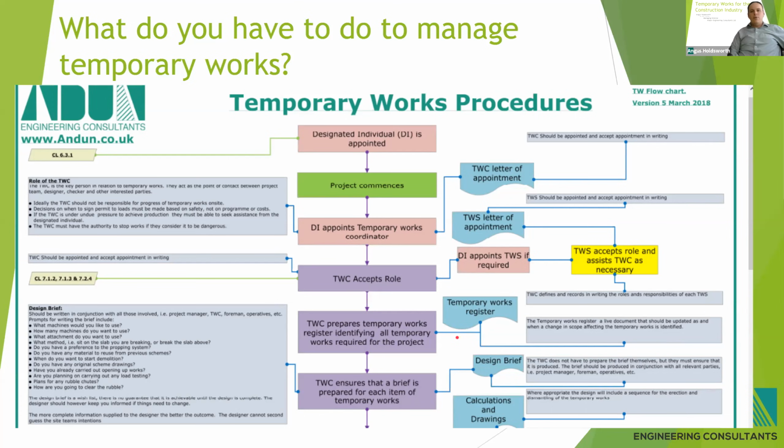So the onus is on the TWC and the designers to say that I think this needs a high level of check, and there is lots of guidance available on where things should sit in terms of risk and therefore checking level, but there's never one size fits all, and it relies on the competence of the TWC and the designers to say, I think you need to do a more independent check here, or I don't think this can be Cat 1, it needs to be Cat 2, or it needs to be Cat 3 because of various factors.